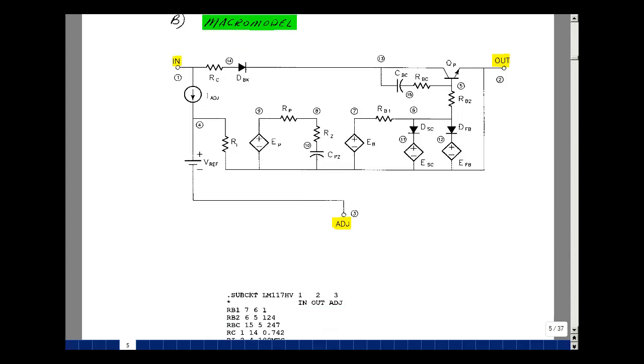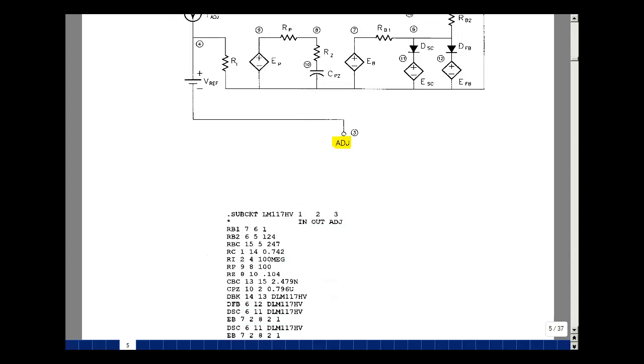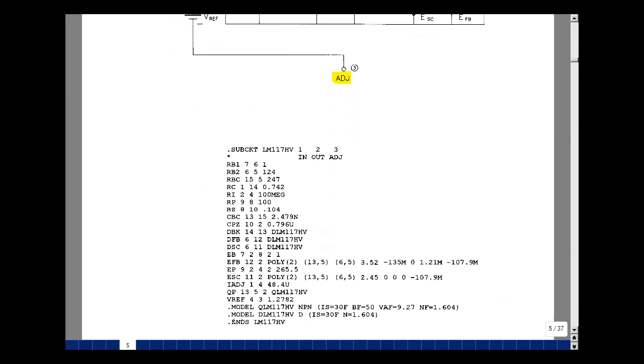So here are the specifications of that model. It has some of our standard parts of resistors and capacitors and diodes, but also these polynomial commands, and this allows me to create a product of terms or to actually shape a curve, and we'll see in a little bit what that has to do with current limiting. Now the development of this macro model I actually teach in another course in macro modeling. It's an independent study course if you're interested.